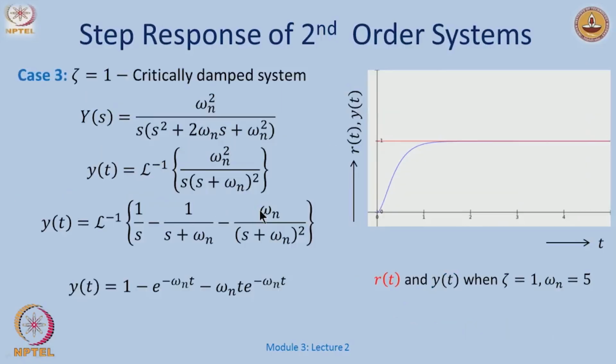Okay. So next, what happens when I am critically damped? I will just skip all this math and see that the sinusoidal terms disappear and I have just this one, y of t is 1 minus e power blah blah blah, right. And I can compute this response either with the final value theorem here or just put t equal to infinity and compute the error, right? The error is again 0. So it goes from 0 to 1 in the shortest possible time and just stays there, right.